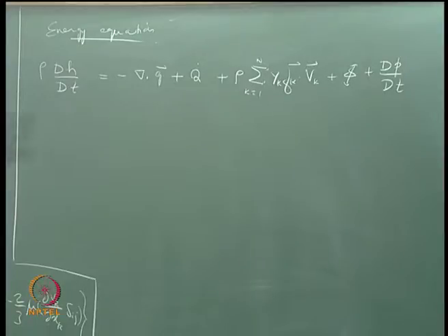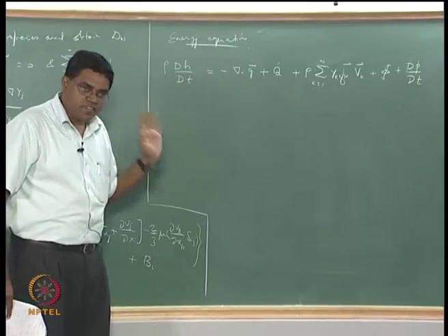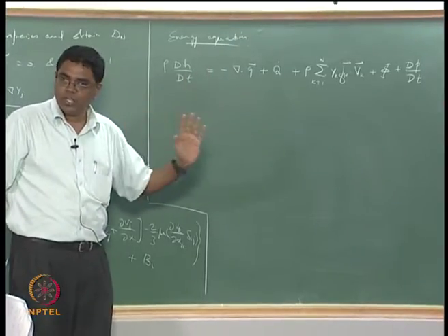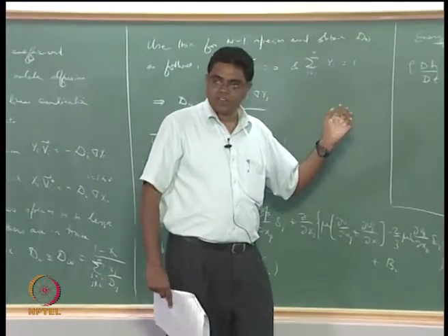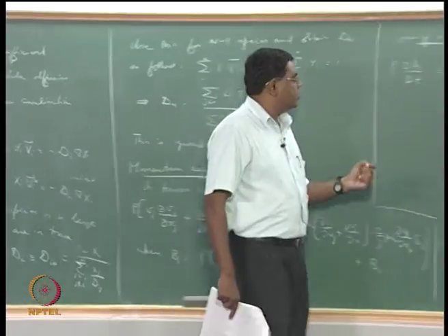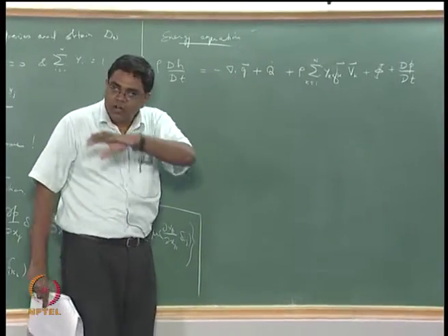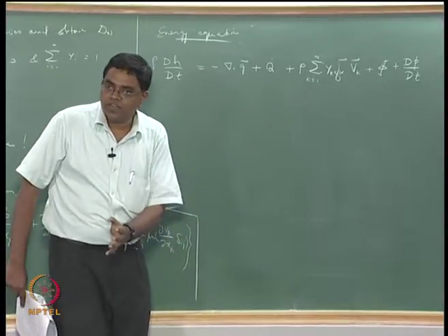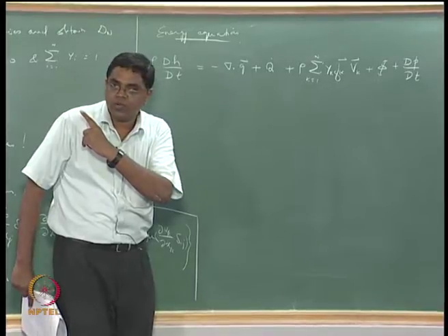That is the operator that we have to replace. This is essentially the inertial term in general, which can now be looked at in an Eulerian frame of reference as an unsteady term and a convective term together, right. Now if you were to derive this for yourself, you would understand that you got the divergence because this was actually a surface term in an arbitrary control volume. This is the way we actually got our species conservation equation derivation, okay.